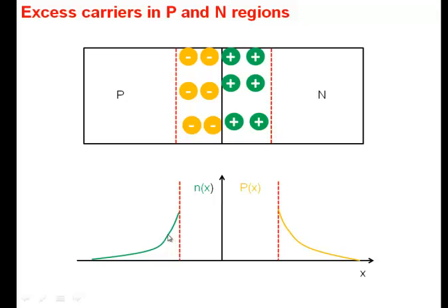So I have charges, and we call these charges diffusion charges. In contrast, these charges here are due to immobile donor atoms and immobile charged acceptor atoms. So this is a depletion charge. This one we call a diffusion charge. Why? Because the process which has pushed them over to the N side is a diffusion process. It's the diffusion process which pushes the holes from P to N. So these charges have come as a result of a diffusion process, and so this excess charge we call a diffusion charge. And similarly, these electrons we call a diffusion charge on the N side.